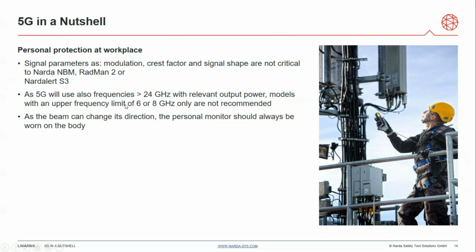As 5G will also use frequencies above 24 gigahertz with really relevant output power, we of course need to focus now on models which are not limited to frequencies of 6 or 8 gigahertz, which was sufficient in the past. But if you want a future-proof solution, you should make sure that you acquire models which have frequencies minimum up to 30, 40, better 60 gigahertz, so that your investment is future-proof.